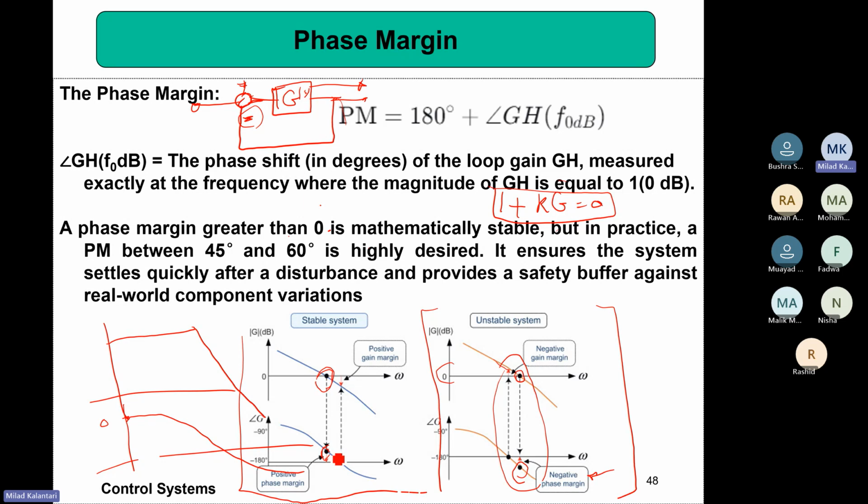But what will happen when we go to higher frequency? At the end, it may reach 180 degrees, right? What will happen? Why is it not unstable? Do you have any idea? I mean, though we are saying this is stable, after a certain frequency, the output phase can be 180 degrees.